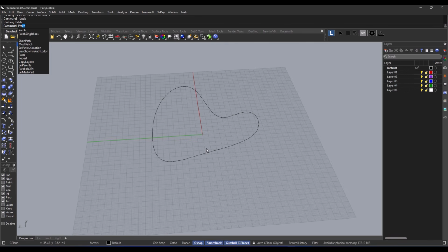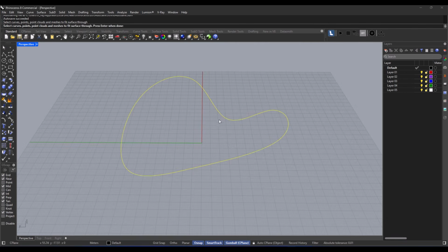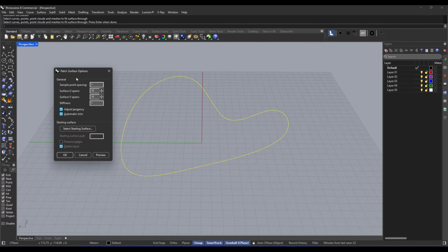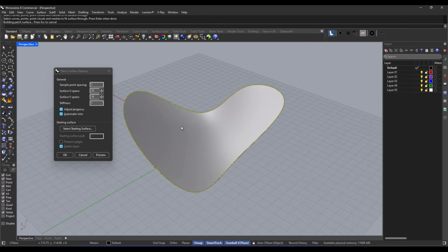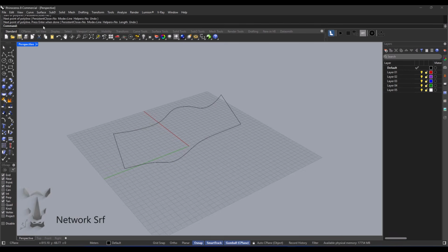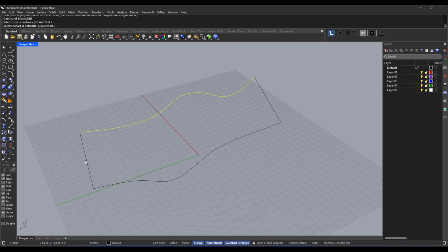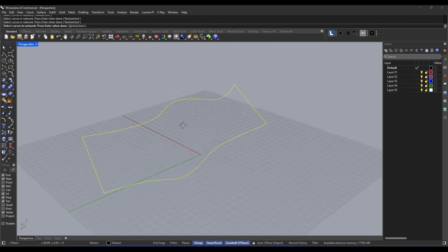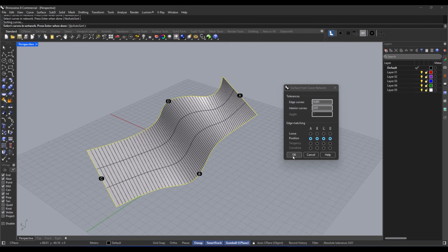First, you have to select the point objects, curves, and edges that you want to base your patch on. Got it? Then you just specify the options. It's super straightforward. Who knew making surfaces could be so simple? Okay, let's talk about the network surface command. It creates a surface from a network of crossing curves. So here's what you have to do. First, you pick the curves in 2 directions that form this network. Or you can just use Windows selection if you want. Super easy, right?